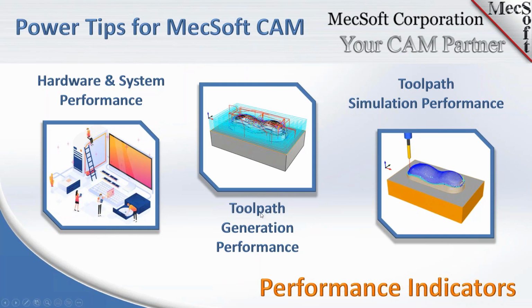In the middle here, we see toolpath generation performance. We mentioned it just a moment in the previous slide. Higher accuracy, longer it takes to generate your toolpaths. Again, on the right, simulation performance, the same goes there. The tighter the tolerance, the longer it'll take to simulate. But we have shortcuts that I'll show you for simulation, so you don't have to sit and wait through an hour of simulation if you don't really need to. So let's go talk in more detail on 3 of these topics.